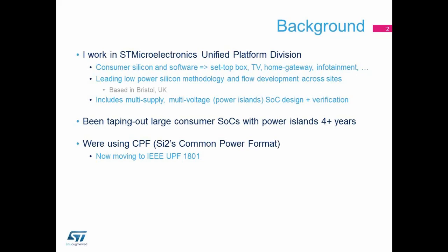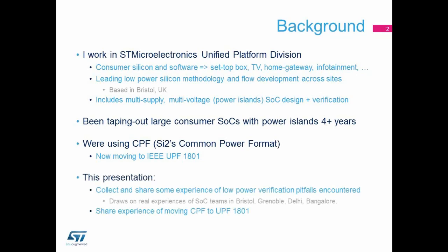So that's something I'm going to talk about a little bit later, about the change now, because we're moving to IEEE 1801 UPF. Purpose of this presentation, really two things. It's almost like two presentations in one. One is to share some tips and some traps that we found during the last few years of low power verification on SOC designs. And the second thing is to share some experience of moving from CPF, power intent, to UPF 1801 on the project that we're doing now.